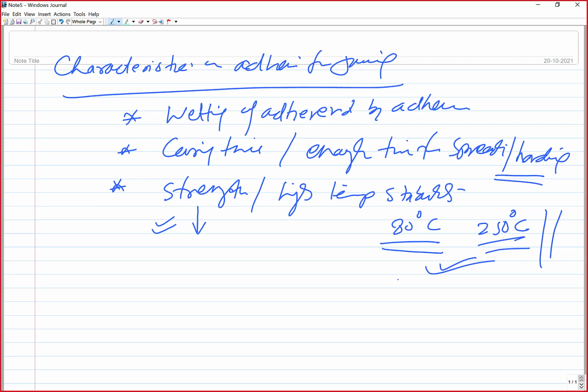Sir, for two-wheelers, we don't use any adhesive joining, but it is mostly used in four-wheeler industries, sir. Maximum they'll be using structural adhesives, which cure at around room temperature, curing automatically. Okay. So in automobiles these may not be in two wheelers, but in four wheelers and in aircrafts these are extensively used. Even in helicopter rotors these are extensively used because they offer huge improvement in the fatigue life of the joint.